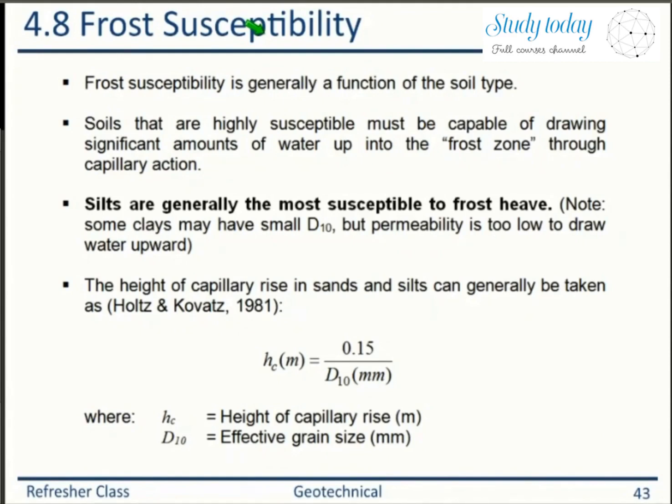Okay, so now if you need to use construction material or backfill material at a site, you will avoid using backfilling materials or structural fill material if it is silt, because the voids in silts are such that capillary reaction is more pronounced in silt soil compared to other types of soil.